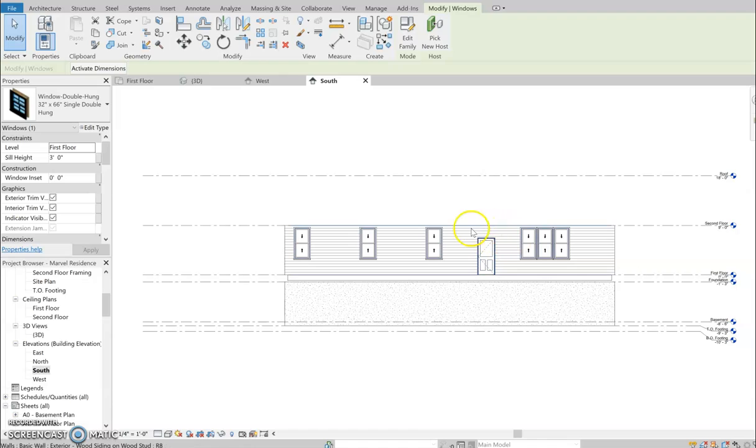You usually want all of your windows and exterior door tops to match across the entire building. So if you do want a taller window and a 9-foot ceiling height, wall height, we could add a transom over the front door. Or we could get an 8-foot tall door because you need about a foot, okay? A foot for a header height.